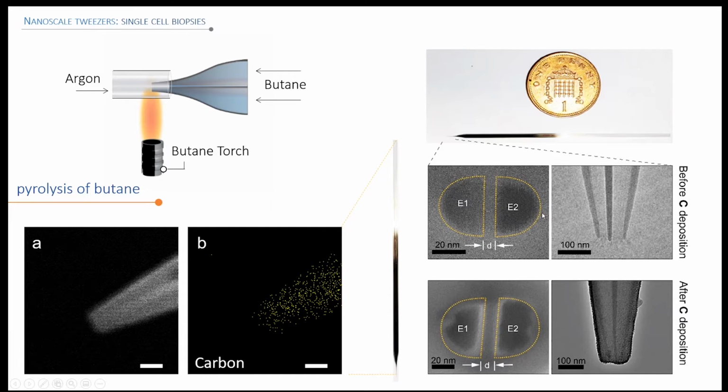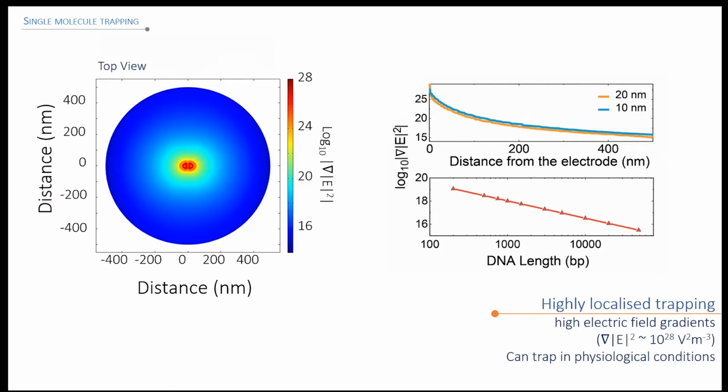As you can see in the SEM and TEM images, the nanotweezers consist of two coplanar semi-elliptical electrodes of approximately 20 nanometers in diameter. The two electrodes were separated by a quartz septum of 10 to 20 nanometers in width. Elemental analysis of the fabricated nanotweezer confirmed the presence of a continuous carbon deposit inside the nanopipette. The close spacing of two coplanar carbon electrodes offers the possibility of generating high dielectrophoretic forces without employing high voltages.